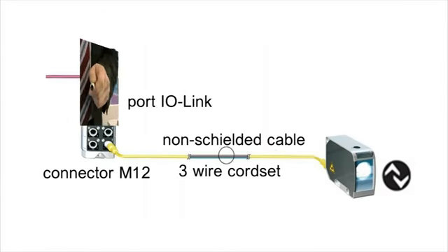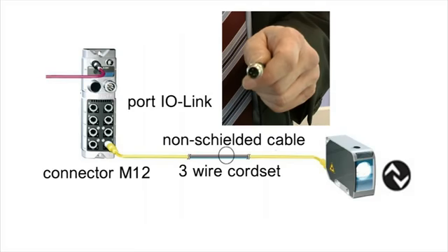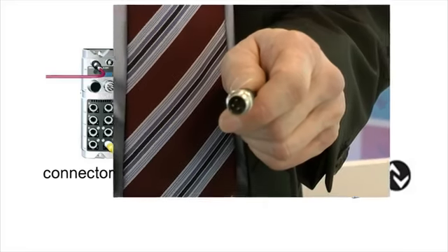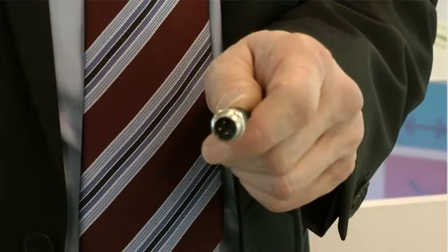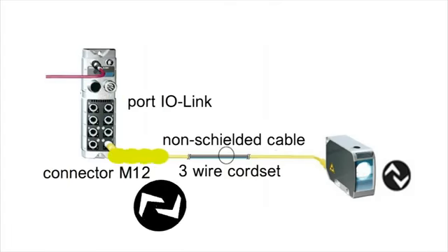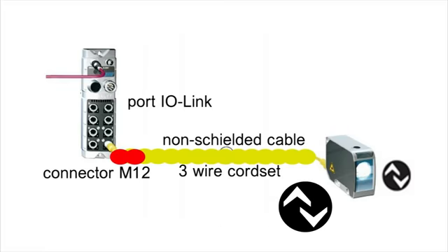IO-Link uses the familiar low-cost and unshielded standard industrial three-wire cable for all connections between IO-Link interface and sensors actuators regardless of their complexity. IO-Link sends the communication signal across the same three-wire cable used to supply the 24-volt power to the sensor. In this way, IO-Link adds intelligence and flexibility to a standard commercial unshielded three-wire cable.